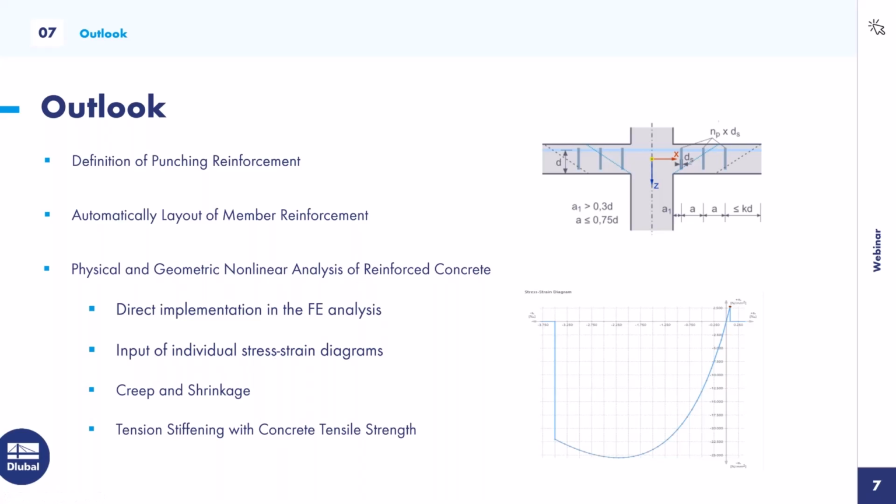On the one hand, with the modification of the Young's modulus, the so-called EEM method, which we already used in RFEM 5. And on the other hand, we will use so-called Kelvin-Maxwell chains together with the add-on Time-Dependent Analysis. With this new development, it will be possible to consider in the add-on Construction Stages also the time-dependent material properties of the concrete.